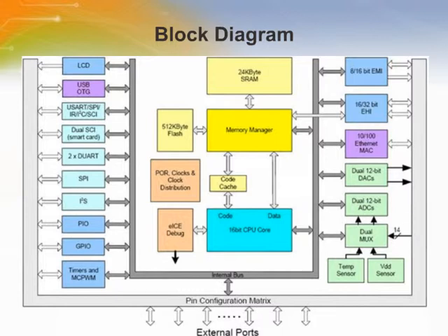The external host interface, or EHI, enables fast data transfer between eCOG1X and an external microprocessing device. The eCOG1X includes an Ethernet MAC peripheral, which can be used with a suitable external PHY device. It also has a USB 2.0 compatible peripheral supporting low speed, high speed, and on-the-go modes.